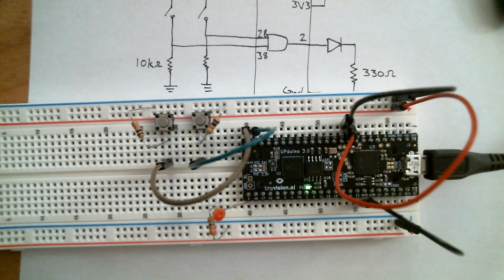In general, it doesn't help to just rip everything out and start over, or just to try random stuff and hope that you'll find the right solution. The best way is to break it down and figure out what you expect at each part of the circuit and check that with some kind of instrument. So obviously a multimeter helps, but you can even use an LED to poke around and examine whether a particular point is high or low.